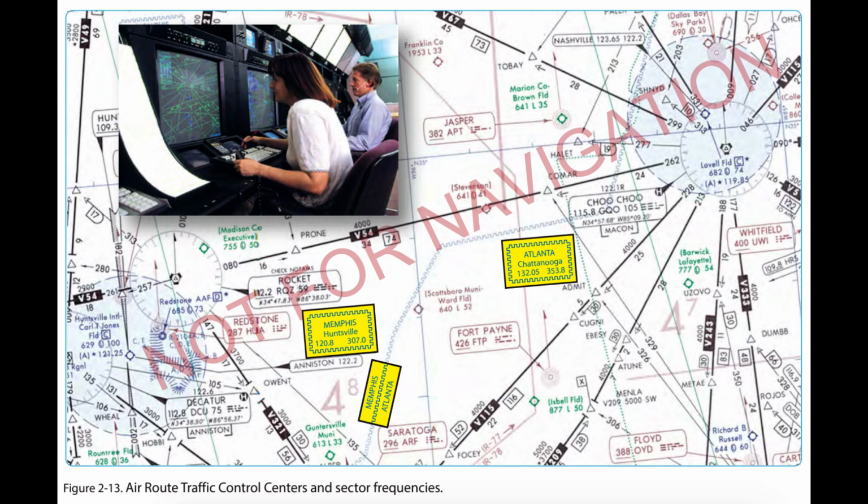The handoff procedure is similar to the handoff between other radar facilities, such as departure or approach control. During the handoff, the controller whose airspace is being vacated issues instructions that include the name of the facility to contact, appropriate frequency, and other pertinent remarks. Accepting radar vectors from controllers does not relieve pilots of their responsibility for safety of flight.